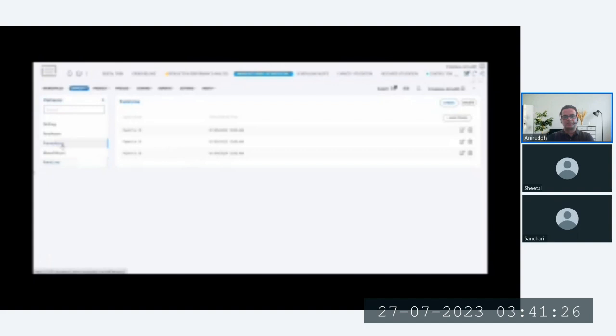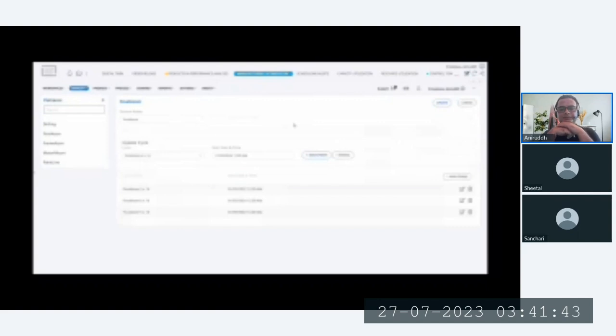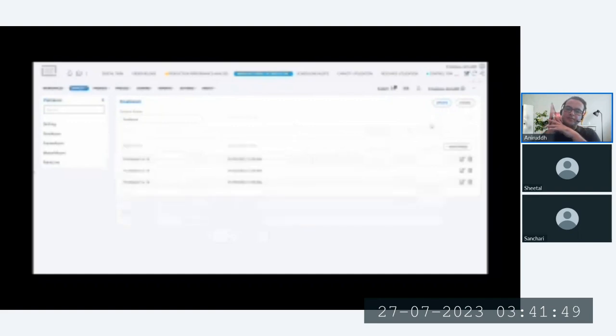So what can we do to remedy this? One of the things that we can do is go to my final assembly operation. I can see that there are different shifts which I've set: five days, 16 hours each, and 6 days, 16 hours each. Currently, the one in effect is 5 days, 16 hours. So let me switch this and make this effective on the 2nd of January 2023. I bring this into effect.